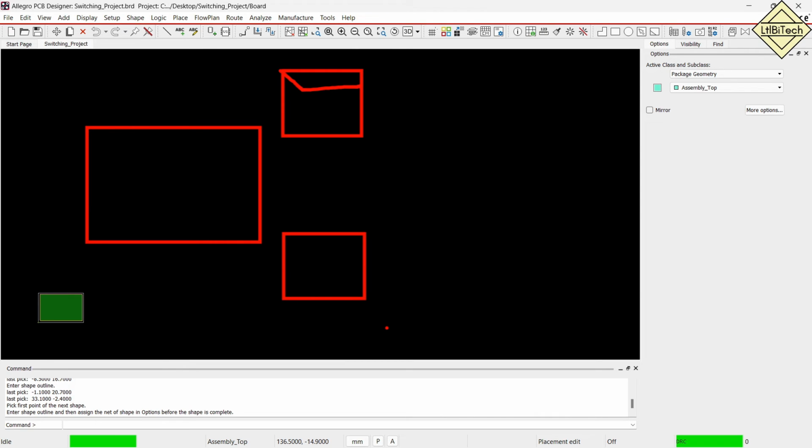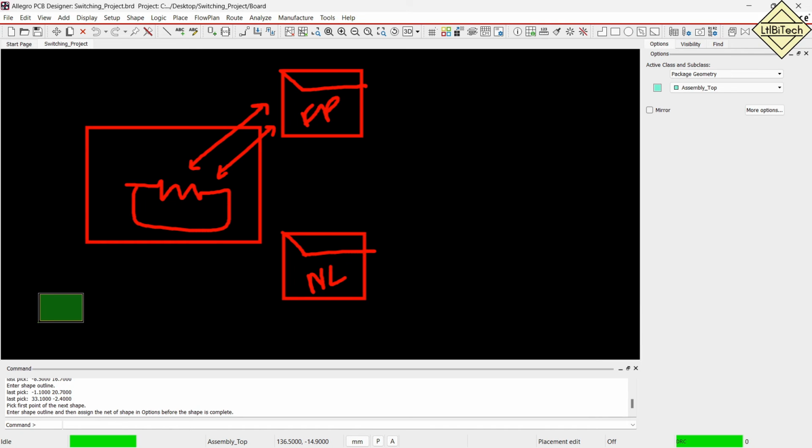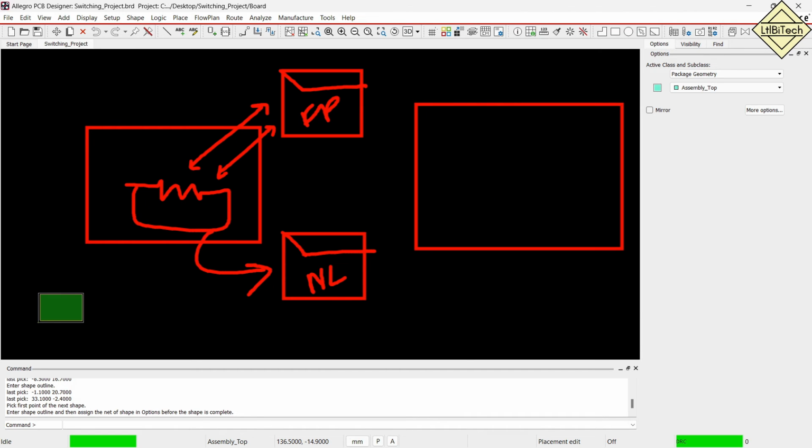So this is a folder for footprints, and this is the folder for a netlist which we created. We have attached the footprints to the schematic symbols, and the net information is exported and stored in the netlist folder. Now we have created the board file, that is the .brd board file. Inside that we have created the board shape, which is 20 by 30, the length and height.